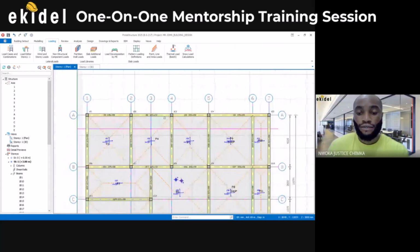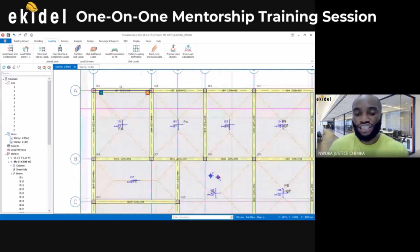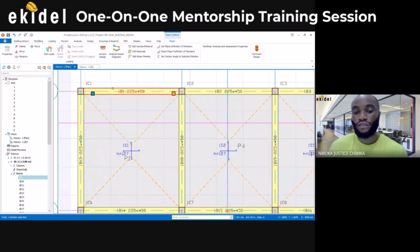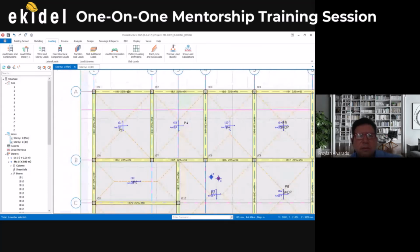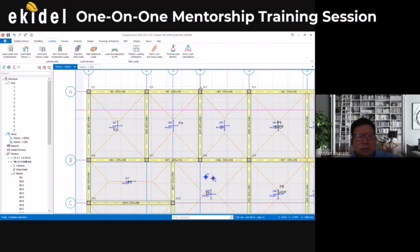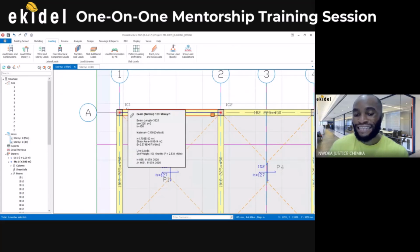I said that once I'm done with my ground floor modeling, before I insert story, I used to hinge my ends of beam. All the ends of beam, I used to hinge it because this software used to give every end as fixed. That's the default. So as it is now, all the beams are having fixed ends. Me, I used to apply pin ends, that's hinge end, to all the ends of my beams.